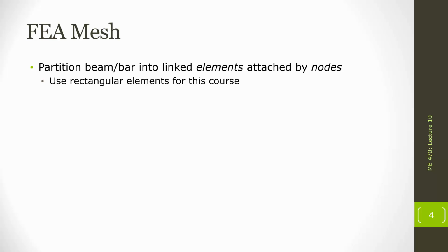But the basic premise we're going to be using here is when we mesh our object and turn it into these smaller shapes or these smaller elements, it will be true within each of these individual elements that it has constant area, constant material, and depending on the type of problem, anything that would need to remain constant in order to solve an ODE at the elemental level.